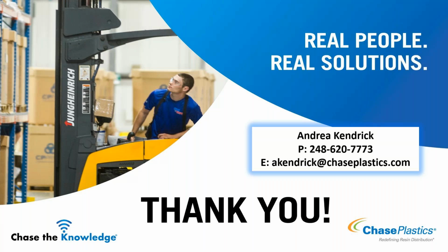If we look at a product as simple as a glass-filled polypropylene homopolymer, moving from a 20% glass-filled product to a 30% glass-filled product is going to show a slight increase in impact performance in a lot of cases. Moving from 10 to 20, you would see the same thing. But knowing that we're adding more glass, we're increasing the modulus of the product. We're increasing the tensile strength. We're increasing the tensile and flexural modulus.